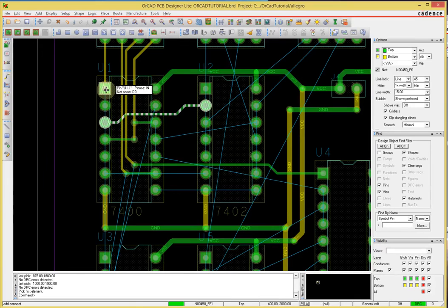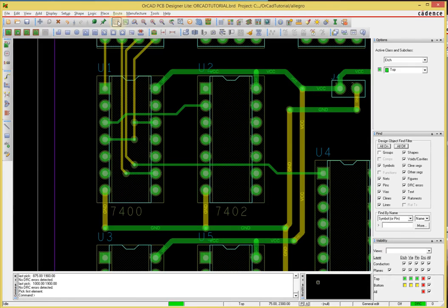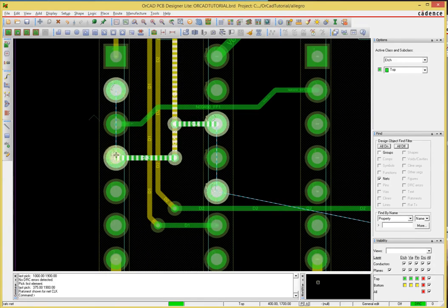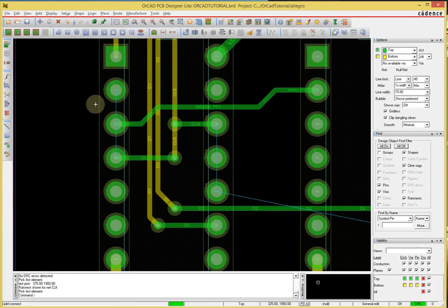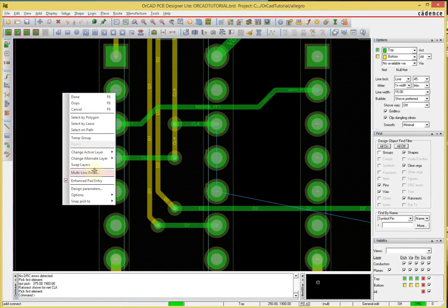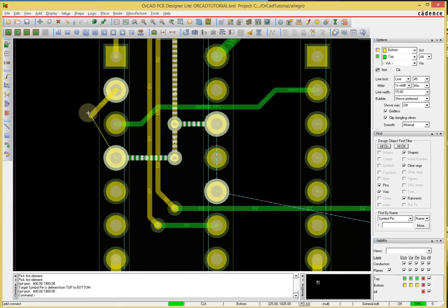Let's see, looks like we need this pin. Where's it going? Let's go and do hide all, and let's do display show rats by net. Let's see, there was a pin here that needed to be connected. I can't see which one it was. If I do that, okay, let's take care of these. So here we gotta short these pins out. All right, so let's go ahead, F3. I'll actually drop the tool for the rats visibility, F3, bottom layer, swap layers. So I'm going to just make a shortcut here.